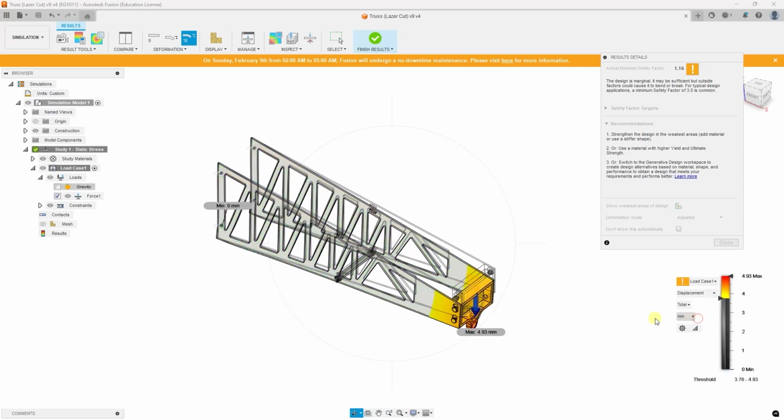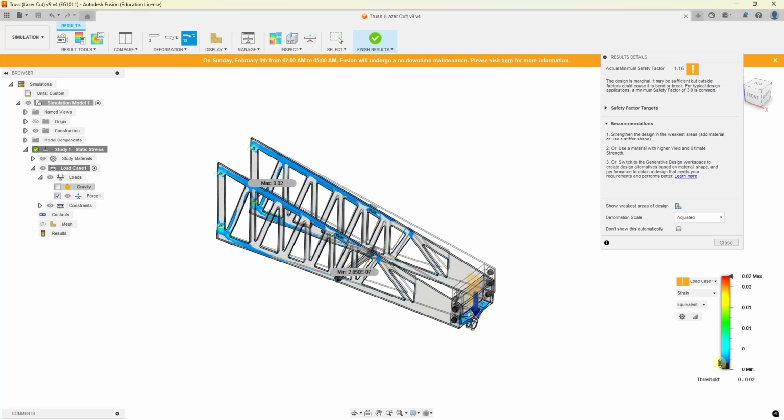You also can see the displacement, and you can see that the displacement is large at the end, where you have the hook to pull the chart down. You also can see the strain, which is the deformations. For most of the crane, you don't have much deformations.